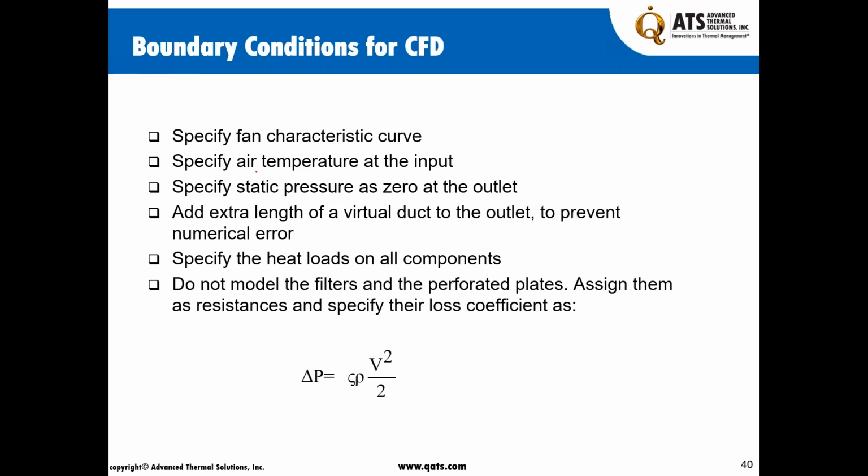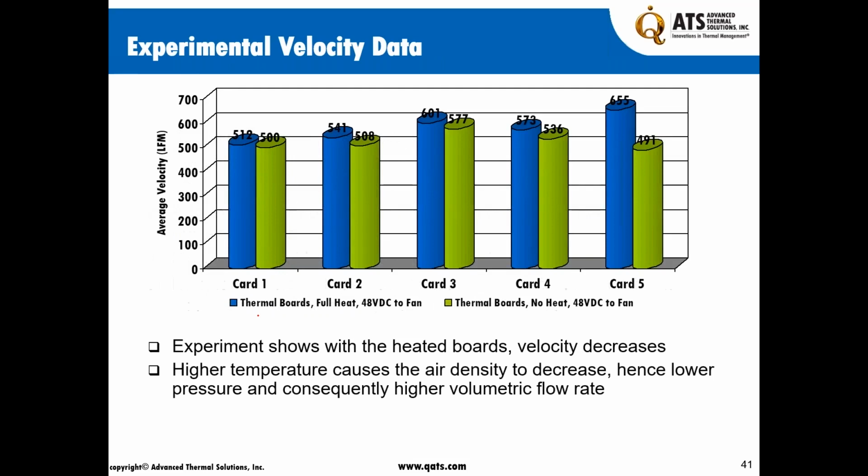Specify the heat loads on all components, and don't worry about modeling all the filter details and perforated plates. There are very good resistance models available for those. That's going to reduce your computation time. Otherwise, you're going to wait for days for the solution to converge.